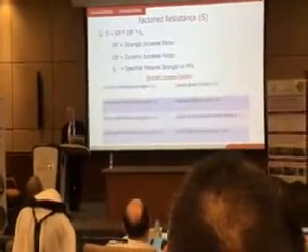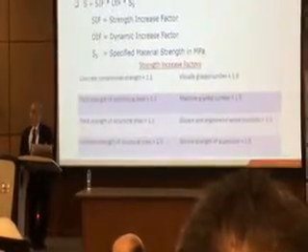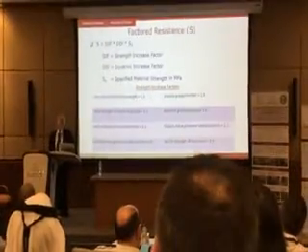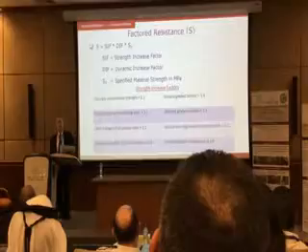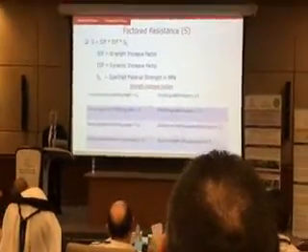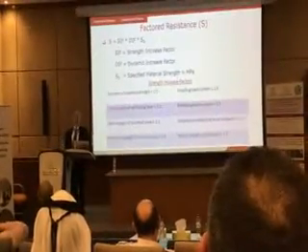Strength increase factor is we use safe values for material strengths. For example, in Canada, our design strength is for reinforcing steel 400 MPa, right? But in the lab, constantly we get 420, 460 MPa. In other words, specified strength is higher than design strength.